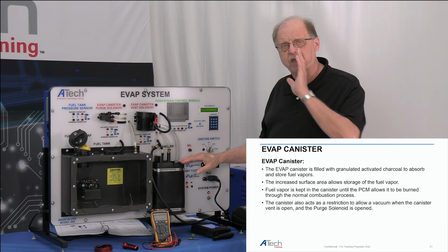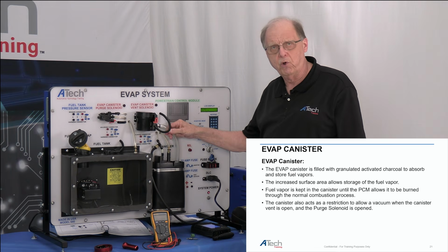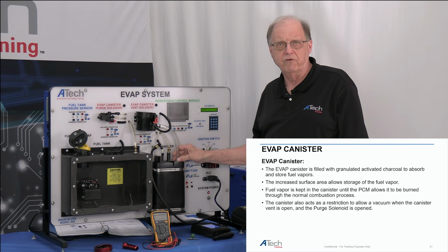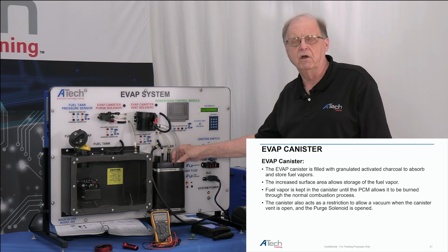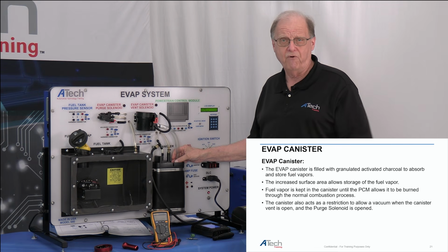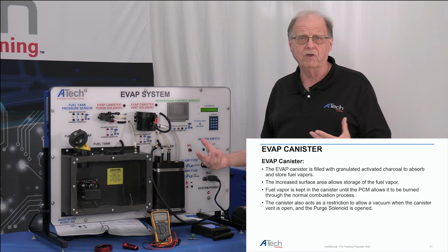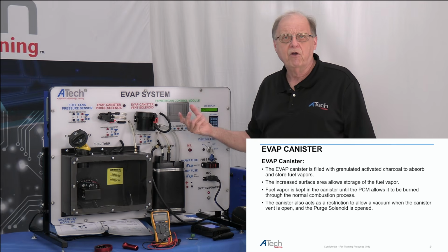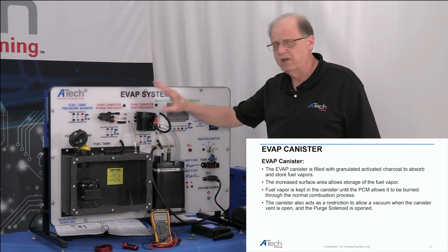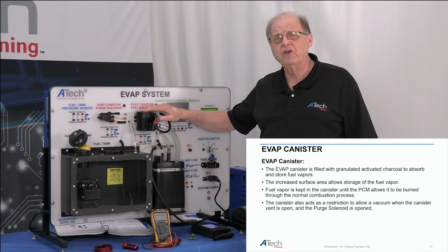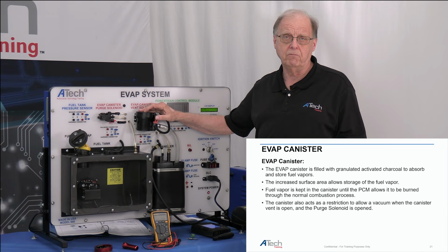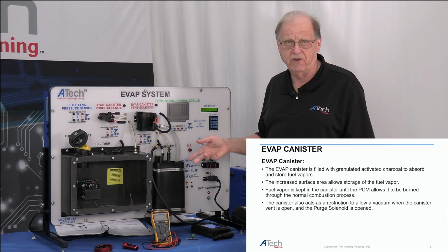The other thing about it is if there is dirt pulled through the canister vent solenoid, you're going to have an issue with this. And that does happen out where I'm at in Kansas, Oklahoma, Iowa, Nebraska, whatever it is, when the farmers are getting their crops in, they will pull some of the stuff into the system. The other thing is Ford will tell you to check the canister vent and make sure it's clear, because spiders will make webs in there and cause a problem. That's another thing you're going to run into, which will affect the system.